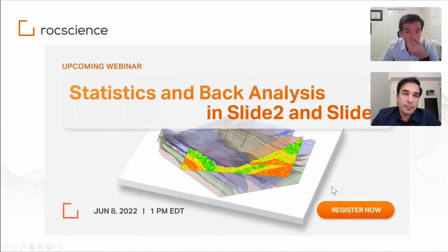So to get the critical state line, you always need some remolded samples. If you have the luxury of getting undisturbed samples, you should absolutely do that, not only for modeling purposes. They serve a lot of other purposes, including confirming your in situ void ratios. And so you would use a mix. Some of the NorSand parameters are not affected by fabric, so they should come out the same from those. Some, such as H, and to some extent chi, the dilatancy parameter, would be affected by the fabric.